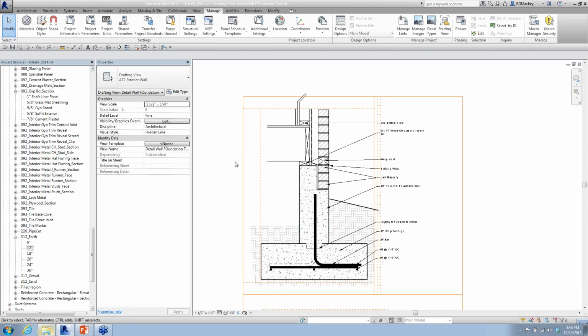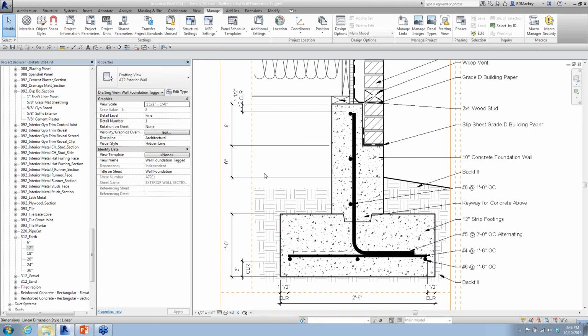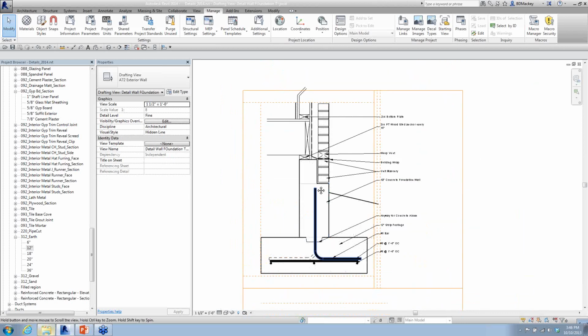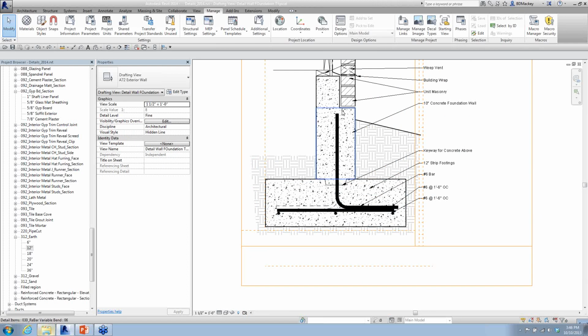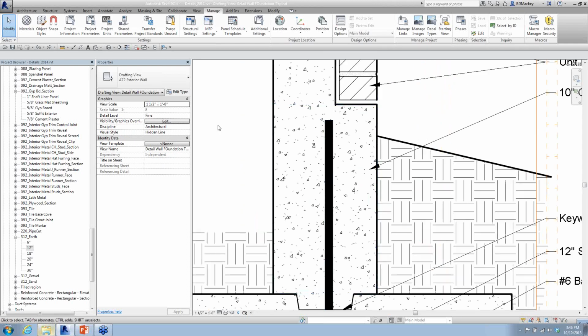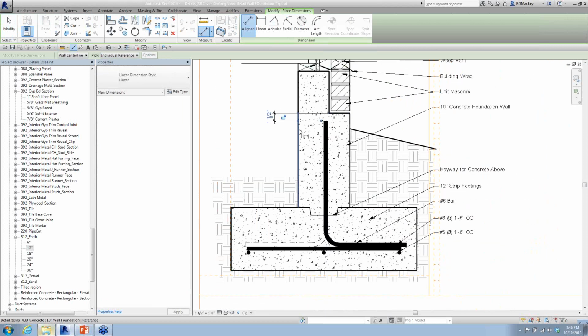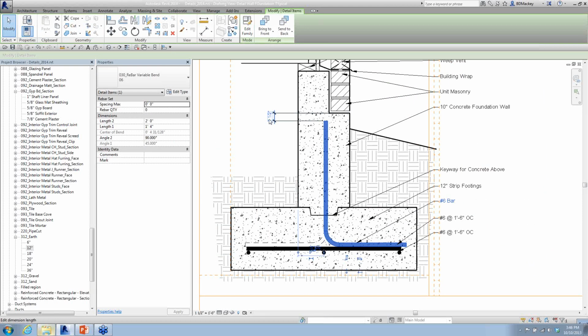So that's really getting into the detailing. Let's go back to that other view and see if there's anything. And then obviously you can start dimensioning as you normally would. And one thing that I always like to start showing people too, so let's just say I needed to show this at 1.5 inches detail away from here. What is nice about the dimensioning as you start going through is if I do come in here and dimension this, I can actually use that dimension as I start moving this object around. So I can come in here and say, oh gee, no, that needed to be 3 inches away, not 1.5 inches.